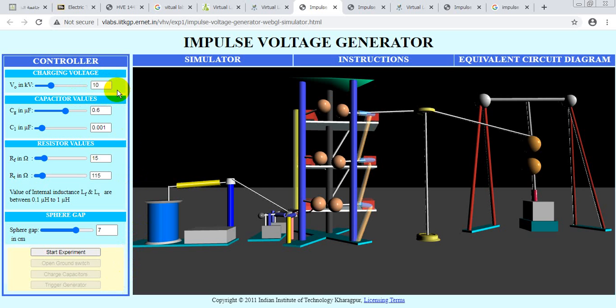In theoretical class, when you were studying high voltage, we did a problem in problem sheet 2, problem number 7, where we evaluated the peak voltage of an impulse voltage, along with the front time and the tail time of the impulse waveform, where the voltage that we utilized was 100 kilovolts. We are giving that 100 kilovolts. Set this to some values according to the problem you have. I am setting the default values here, and to start with, let us set the distance to 2 centimeters, and now press start.